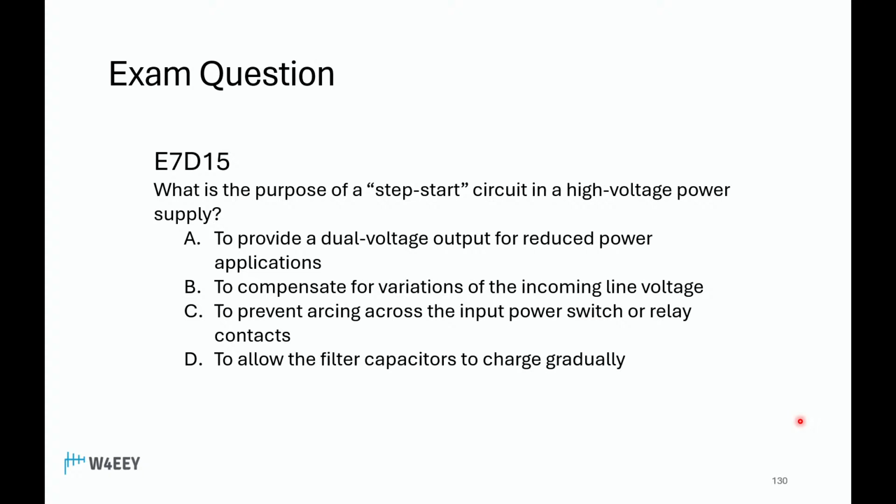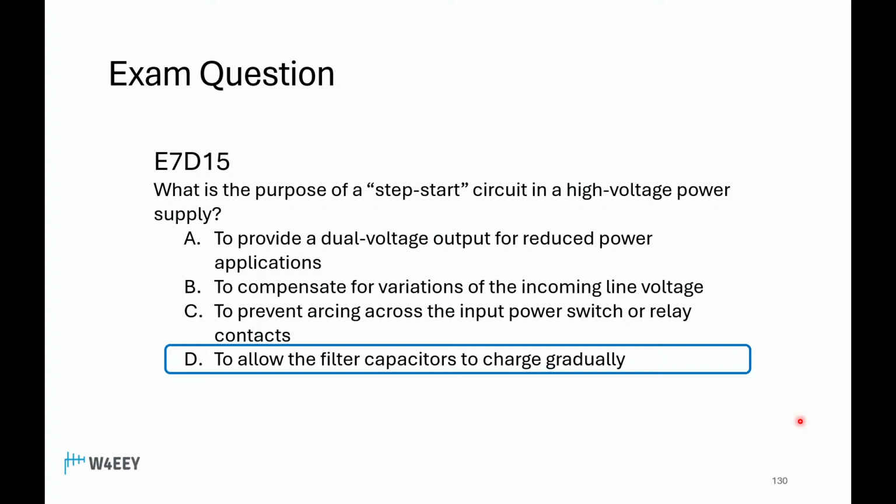What is the purpose of a step start circuit in a high voltage power supply? Delta. Yes, allow the filter capacitors to charge gradually. Correct. All right, the next slide you're going to really like.